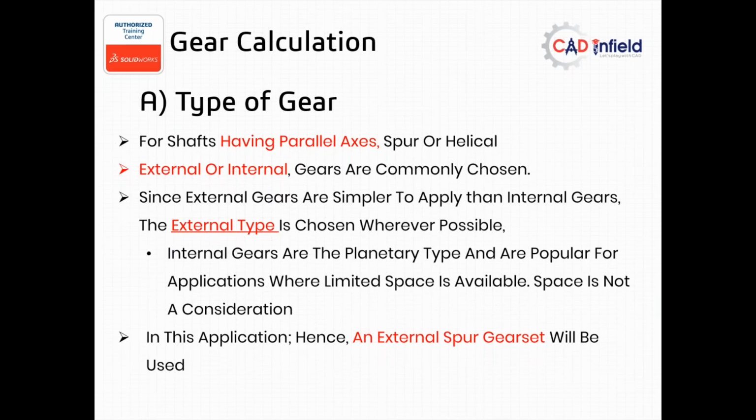External or internal. We know that external gears change the direction; successive gears will change the direction. Most of the time, whenever you have available space, go with the external gear, because it is very easy to design. It is also very easy for maintenance purposes.